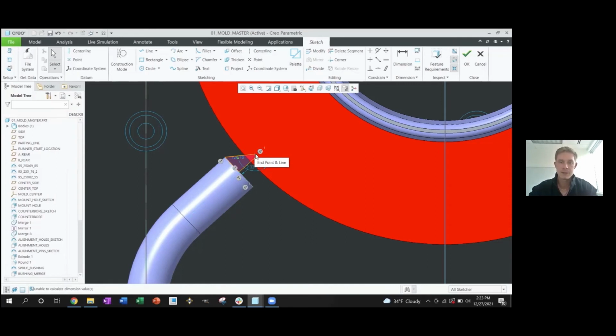For highly viscous plastics with a very low melt flow rating, or filled plastics, things of that nature, we're going to go with a larger gate, something that's close to a 90-degree angle going into the part itself. We're going to sacrifice the gate vestige a little bit in order to improve the actual filling of the part itself and the longevity that the mold's going to have. For plastics like an unfilled nylon, polypropylenes that are lower viscosity, have a higher melt flow rating, that's where we can actually decrease this attack angle so that we have a smaller gate vestige on the part itself.